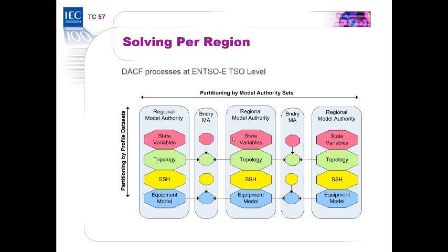So the TSO then take those schedules. A schedule is time series data, so you typically have 24 hours, values for 24 hours. In the congestion forecast, you want to make sure that the power flow gives a feasible result for each hour in that time series. So you map down the time series on your network model and your boundaries.